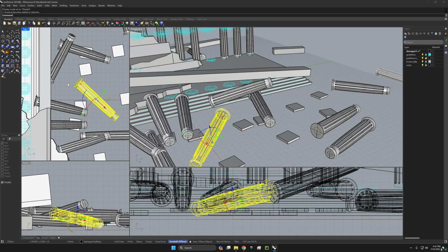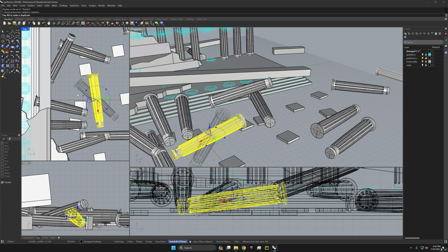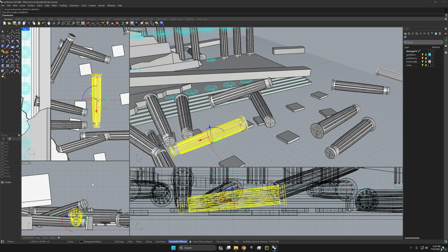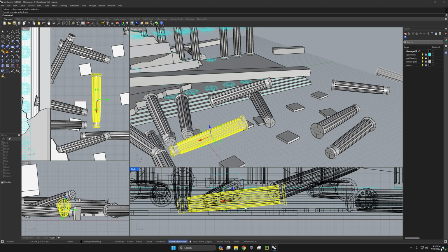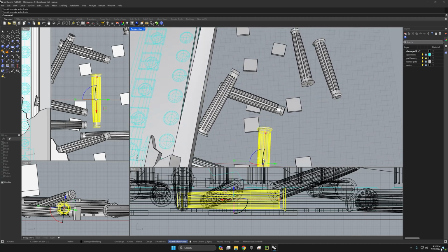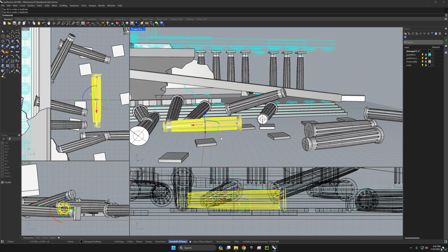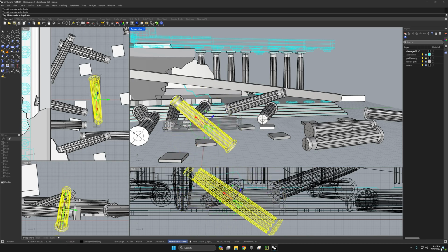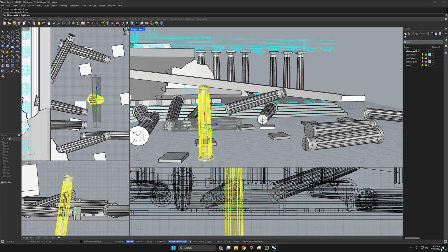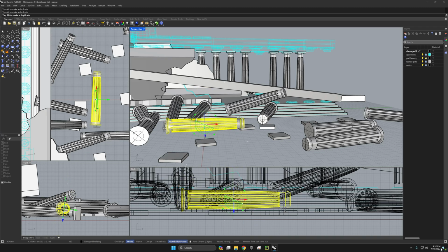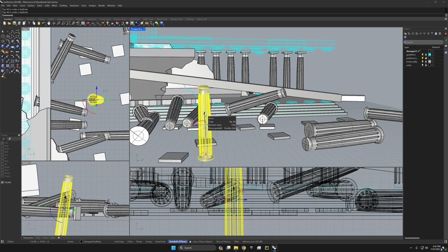Let's run through a quick example together so that you can see how the gumball can be used to move the pillar into place. We'll go to the top viewport and get it to be fairly well lined up with the grid from that vantage point. Then we'll go to the right viewport and check it there. And that's pretty close. Let's go ahead and stand it up. One trick for rotating in 90-degree increments: you can see it moves about freely right now. If we hold Shift, it will toggle ortho and turn it on to allow it to snap 90 degrees up.